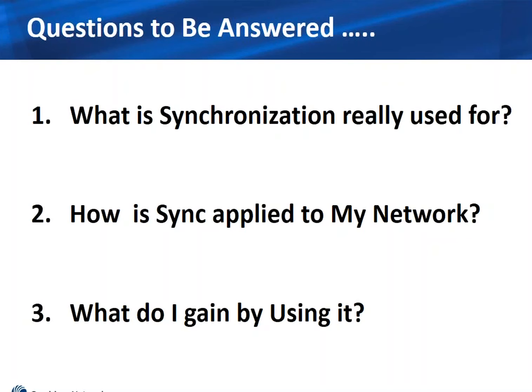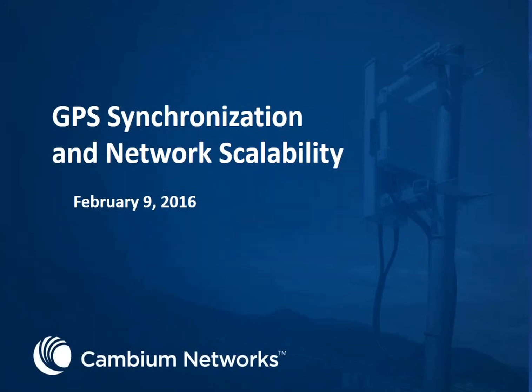Things like having good transmit power control within your radio solutions, having optimal antenna specifications, front-to-back ratios that are optimal to allow you to do a lot of frequency reuse and interference rejection, adjustable duty cycles, et cetera.